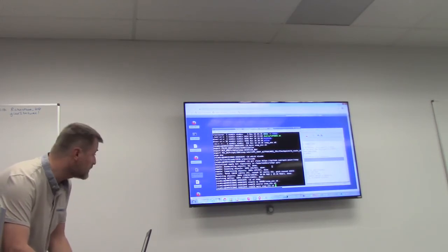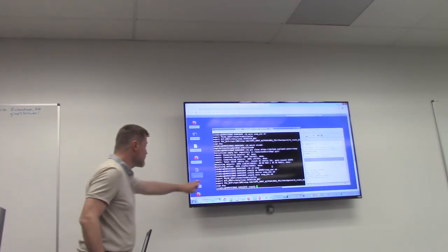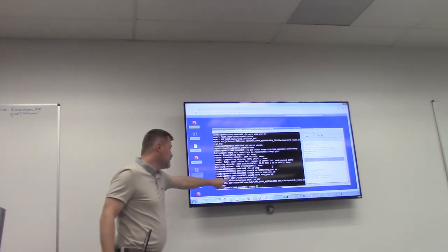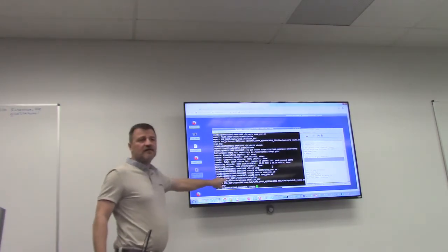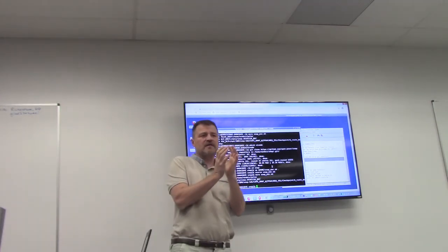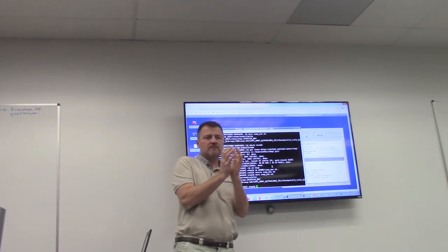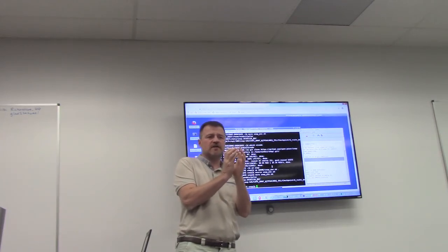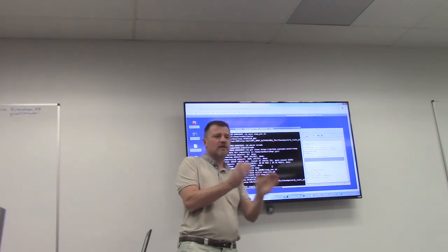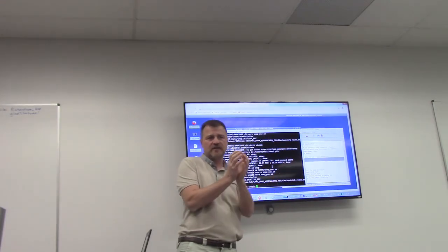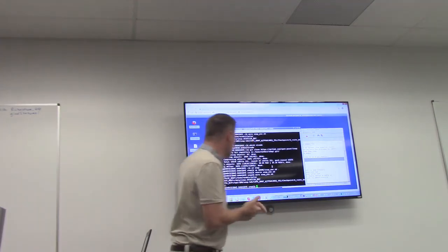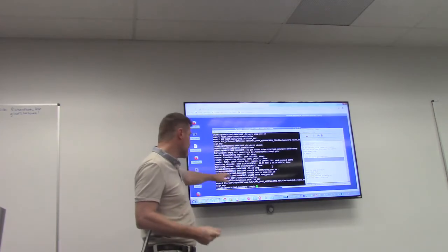So let's have a look at what it is. No magic here. We define three basic standard directories. Export PSLSC. PSLSC is a simulation engine. PSL is the processor service layer. Remember this blue logic that IBM provides to make sure that any CAPI device, your FPGA, will use this hardware and work fine with the POWER processor.